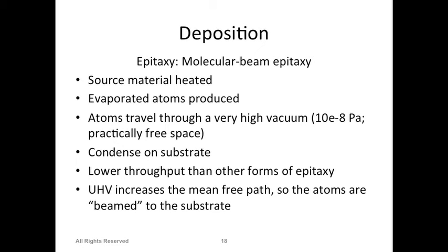So you want to make sure that they don't start getting deposited on the surface without aligning themselves with the bottom orientation. That's the only thing you want to improve. If they are getting deposited very quickly, they will just start depositing on the surface. So they will still make the material silicon, but it will not be in crystalline form. It will be more polycrystalline or more amorphous. It means you have small chunks which are crystalline locally, but not globally. They will not be crystalline.